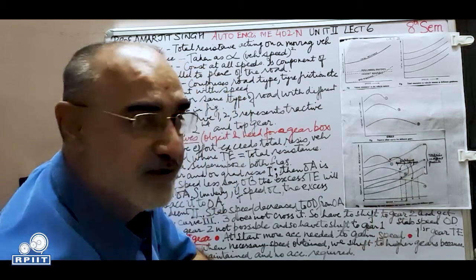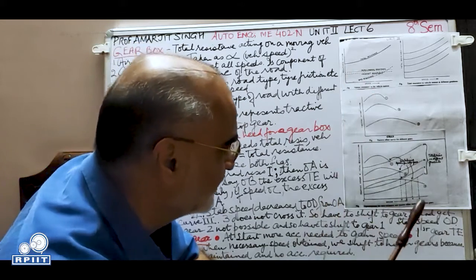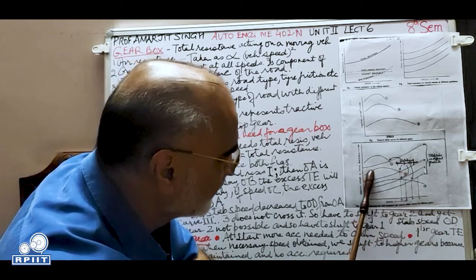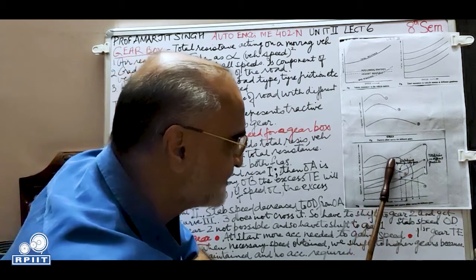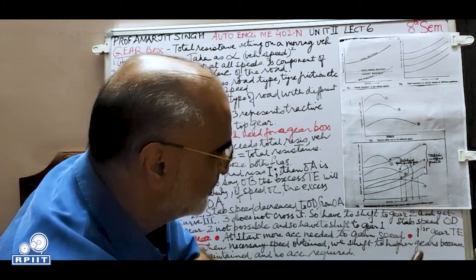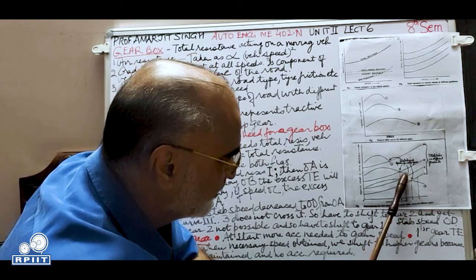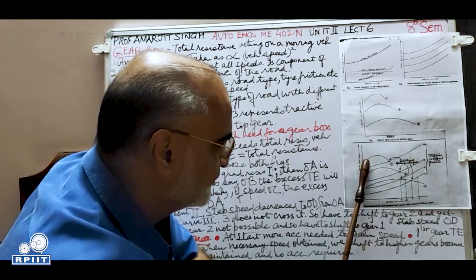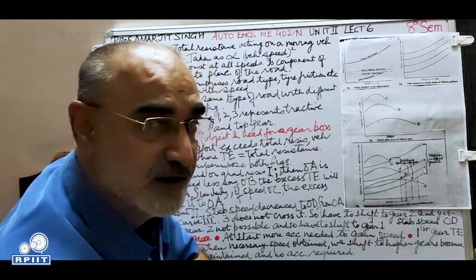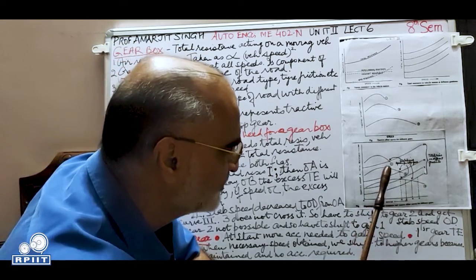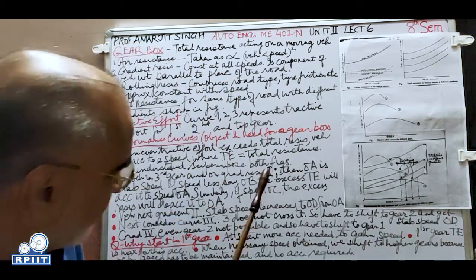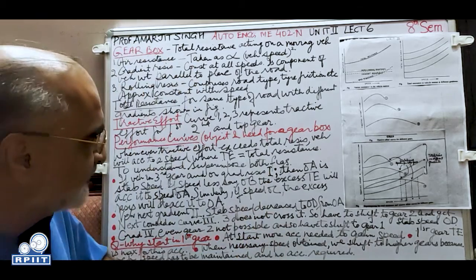Now let's come to the fourth gradient. And the slope increases further for the vehicle. It was in second gear, now the tractive effort of second gear is also less than the total resistance 4. So we have to shift from gear 2 to gear 1. And this tractive effort will be more than this, and so the vehicle will have to climb that slope in gear number 1. And what will be the stabilizing speed in first gear? This. Here. Now we can read this so that once you repeat it, you will understand it better.